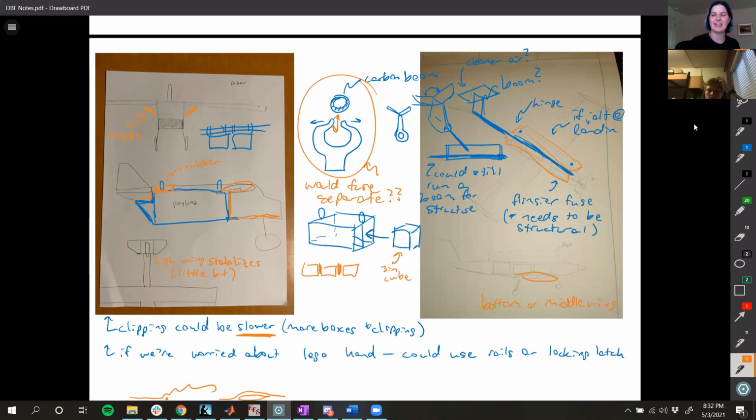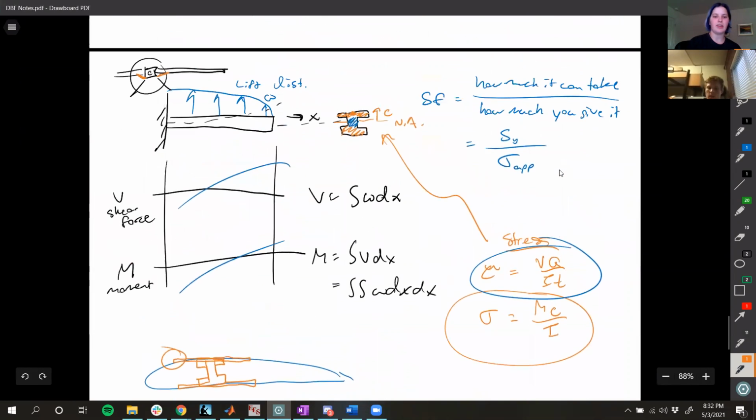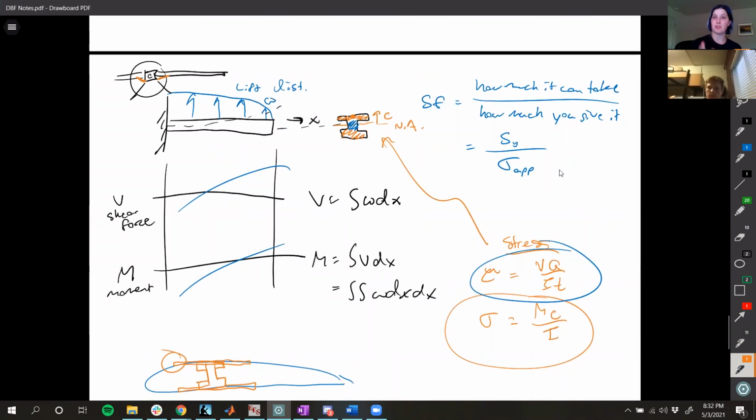I'm thinking we're doing balsa for our wing, right? And we'll have probably some plastic, unless, could we do a thinner balsa wood on the tail edge of the airfoil? If you want to. Is there a difference between that and the plastic? Well, the thing is, it's assumed that all your load is going through the spar, and that everything else is just for the airfoil form.